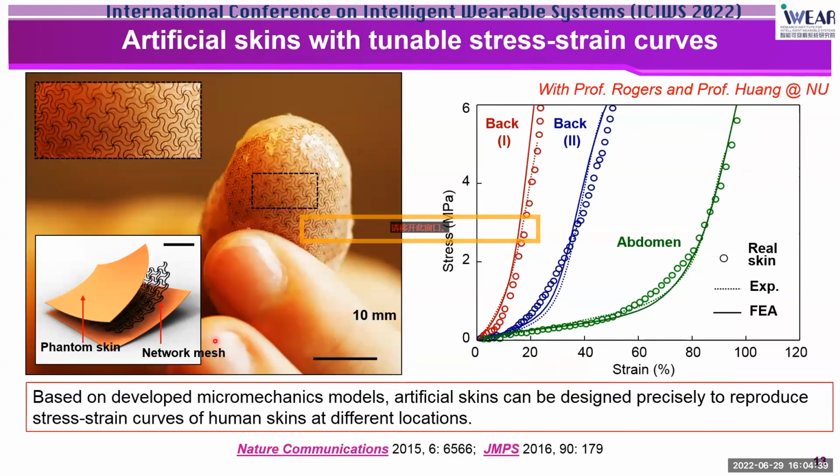By degenerating the 3D helical microstructures into 2D, we can create planar network materials consisting of horseshoe microstructures. And this kind of 2D network material can be tailored to reproduce mechanical properties of film-shaped tissues, such as animal skins. This kind of 2D network material can be fabricated much more easily than the 3D networks. And excluding the 3D printing, the photolithography and the laser cutting technologies can also be exploited. And polymers, metals, and semiconductors can all be used.